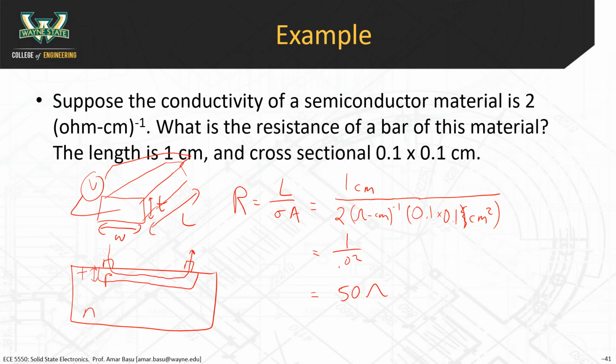Sometimes they're made from high or low conductivity things. In fact, for the basic resistors, most of the time they aren't semiconductors. They're just made from alumina or metal films, things like that. Okay, like bulk materials. So this is just really small, transistor level. Yeah. If you want to make an integrated circuit on a chip, integrated in silicon, you have your transistors, and then you also have your resistors on there, everything integrated. This is how you would lay that out. Okay.